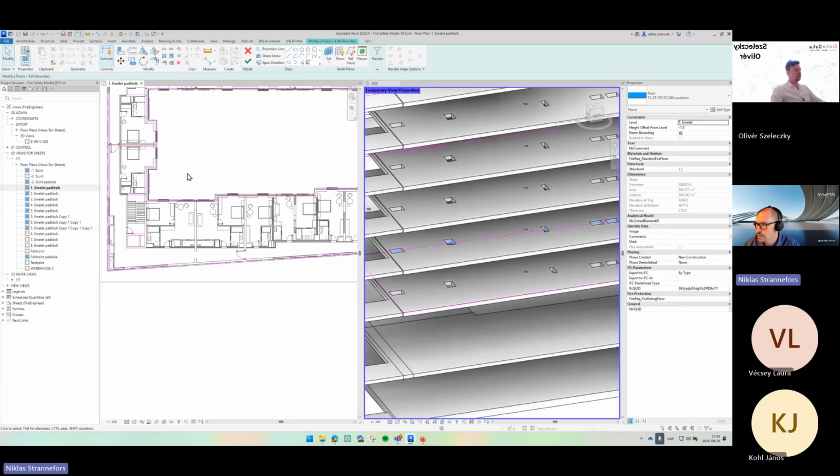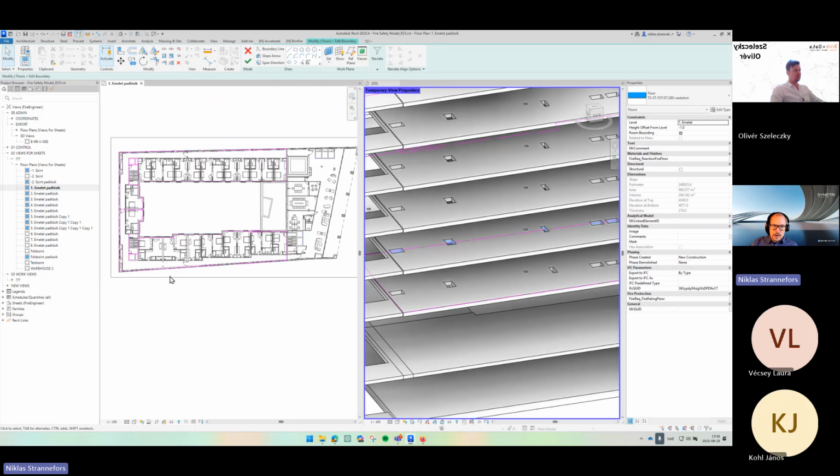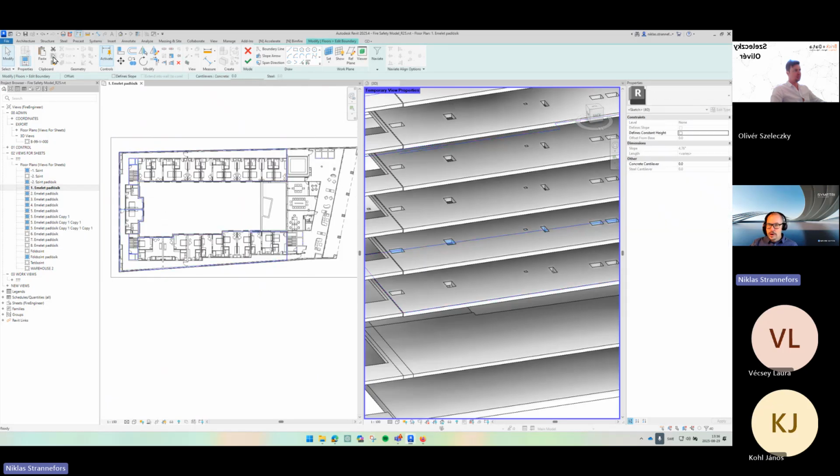Because we are copying every floor one by one, they're connected to each and every one. If you change one, we probably want to change the same layout on several. What we can do before finishing is select all the lines, copy to clipboard, and paste those sketches in the next level. So we draw, copy the sketch lines, and we can copy-paste within the sketches, each and every one of those.